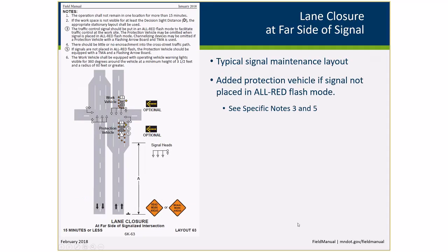There was a pretty significant change to this one. This is what is used a lot of times to change a signal head. The previous layout had nothing prior to this. It just had the work vehicle with the channelizing devices around it. And there was a statement up here saying that the traffic control signal should be put in all red flash